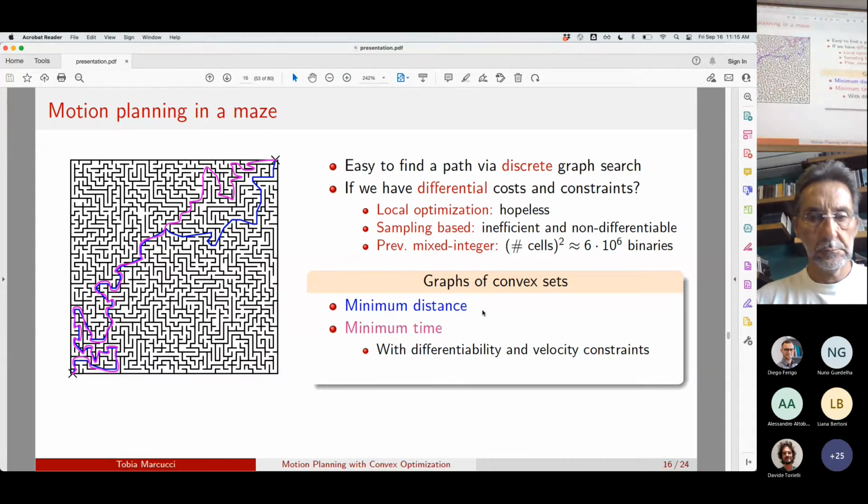Yes, I actually had to cut that part. I left the introductory slide, but didn't include the numerical results. On those kinds of problems, let's say you have a simple dynamical model, kinematic limits plus second-order dynamics, and 30 stepping stones randomly generated in the environment. Our tests show that where previous methods would take tens of minutes, we are of the order of a second in those planning problems. So we are, I cannot do the math on the fly, like 600 times faster.